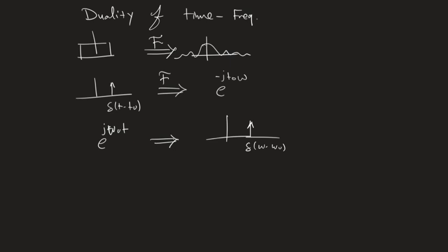And the same applies to everything. So we can go up there and say, if I had a sinc function in time domain, and I try to look at its Fourier transform, by comparison and by analogy, it will be a square function in frequency domain. Okay? Now, why do I care about this particularly, and why did I do all of this and talk about the duality to discuss this? Because this function, which is a square function in frequency domain, anyone wants to ask anything before I leave this slide?